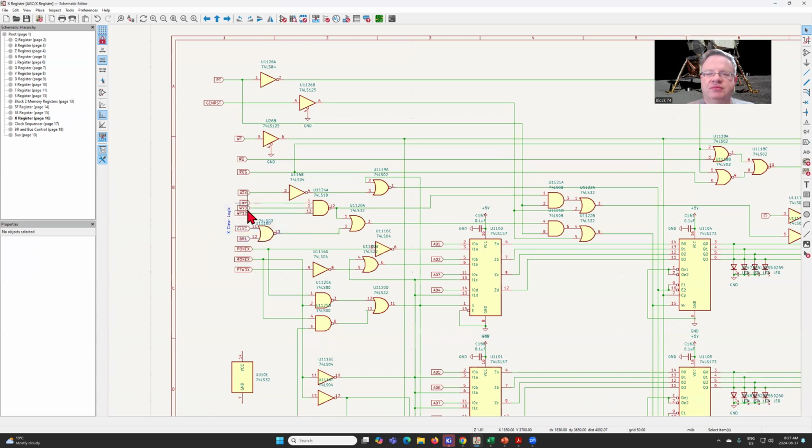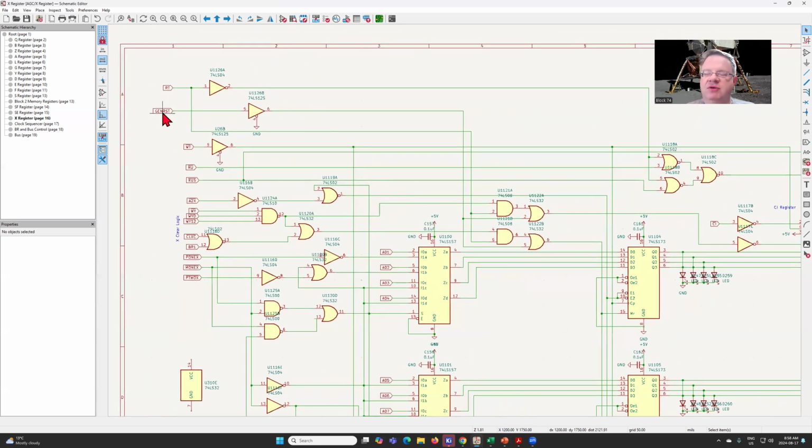So we have basically this logic where, if we have any of these pulses or this combination of these two pulses that we bring together, and then we also have our general reset. If we want to press the reset button on the computer to clear out everything, we have this signal coming in, and that's all combined together along with our read timer. So we'll clear this out when our read time pulse comes through. And we generate two of these reset signals. One of them is going to actually reset all of the register contents, so set X to 0.